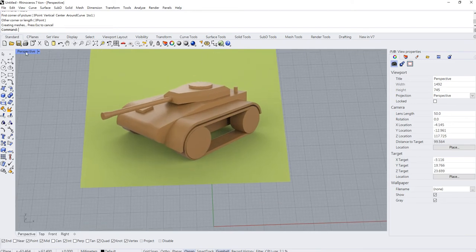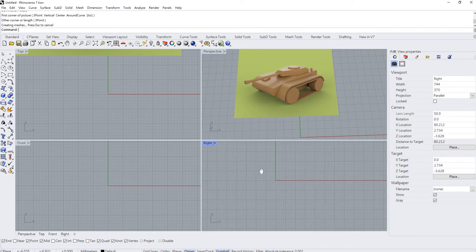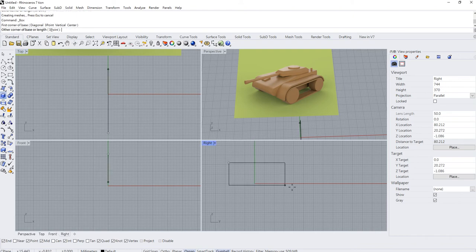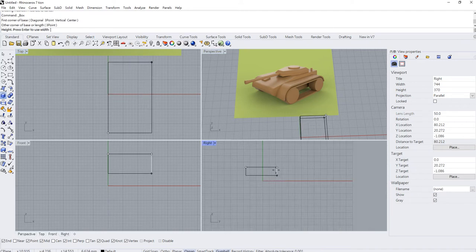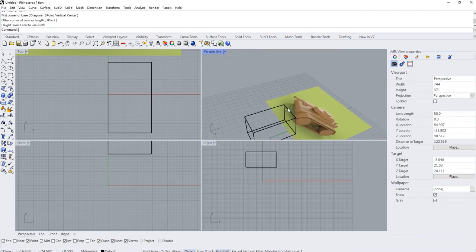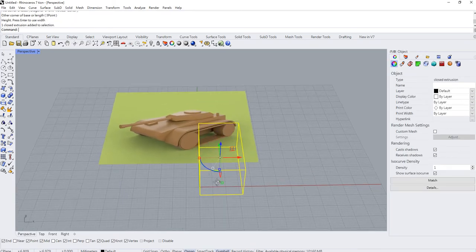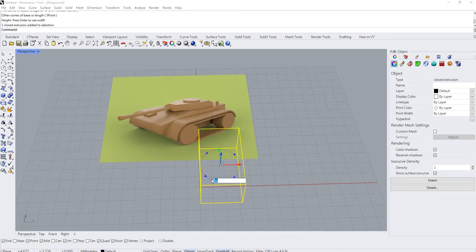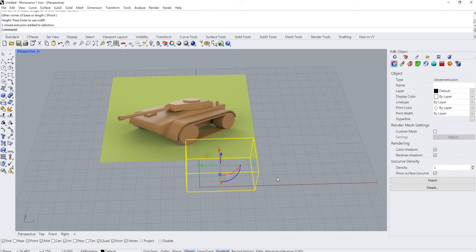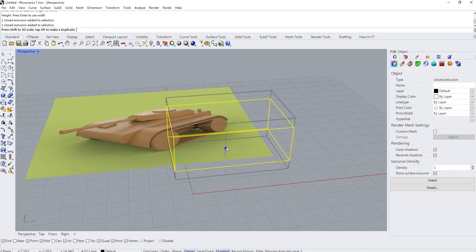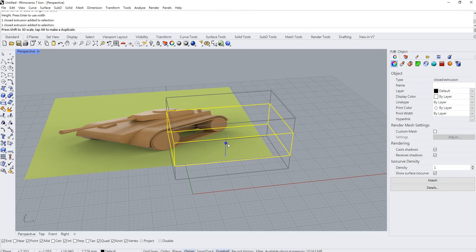It's very simple. Let's go to the side view, probably the right view as well. Let's just create a cube. And to the side. Okay, that's the cube we made. And let's rotate this one 90 degrees, so probably it will fit the image we use. It's supposed to be more flattened, so let's scale in the blue direction. Hold on the blue box.